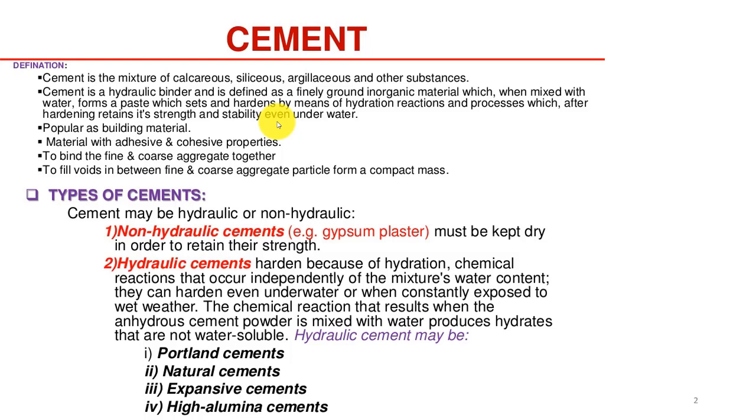In this case, cement particles, whose average particle size is around 30 microns, would occupy the spaces between the fine aggregate and the matrix, so that you can have an adequate density to be called concrete.